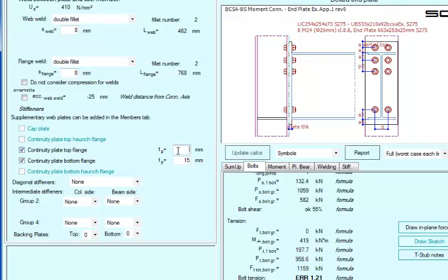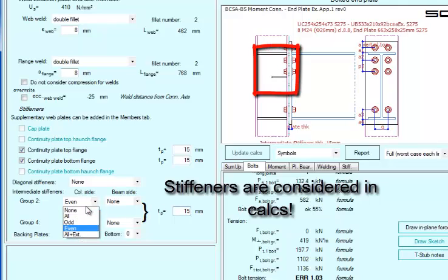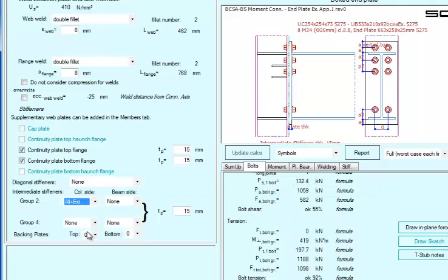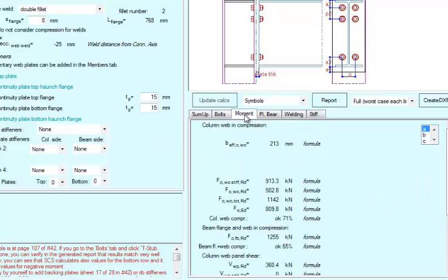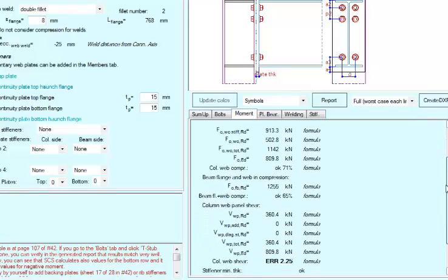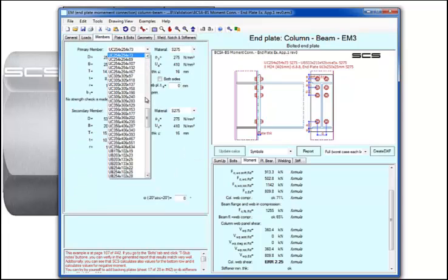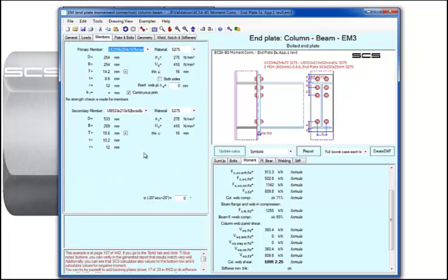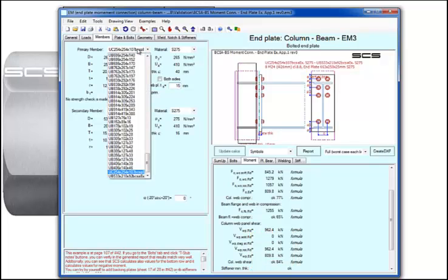The full depth tension stiffener can be added on top, and intermediate half depth stiffeners can be inserted between both rows. Since the connection is double-sided, web panel shear is not a design consideration, as explained in the SCS Manual, paragraph 27.4. SCS suggestion, though, is to conservatively design a connection satisfying this requirement. The book too designs a 15 mm supplementary web plate for the original column size.